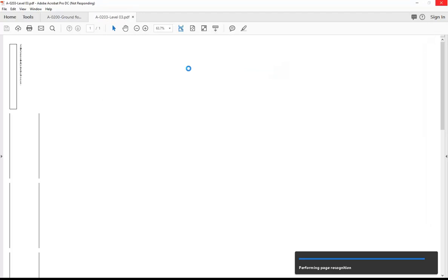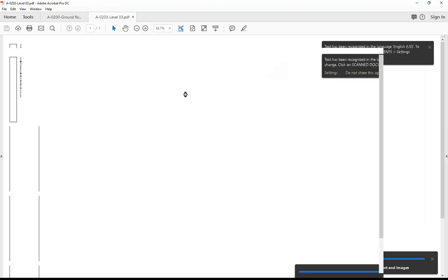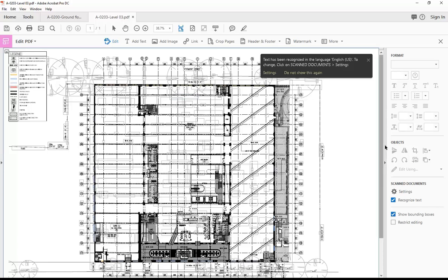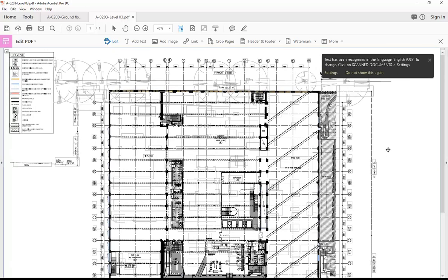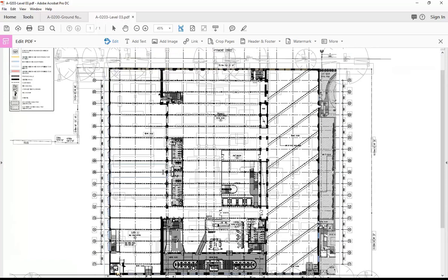Now, honestly, I'll tell you the way I would do this. If it was a PDF from a firm like this, where I know they use Revit, I'd be trying to make this into a DWG file, maybe, to get vectors. But it's going to take me too long to show you that, and it's probably not worth it if you're not really familiar with AutoCAD anyway. If you are very familiar with AutoCAD, that's something you could try, because it'll be vector, and you don't have to work with a JPEG. But look, JPEG's okay.